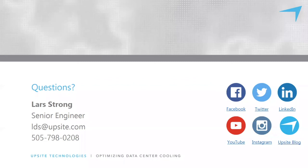Yeah. So there's some more good points being brought up. Appreciate them. So PUE, there's both instantaneous and then trailing average. There will obviously be some variation in the amount of cooling required by the season, and I appreciate this listener bringing this point up, because one of the things I mentioned was heat load in the room, and power in, heat out always. And if you know your UPS output load, you have a good idea of what the cooling load is.